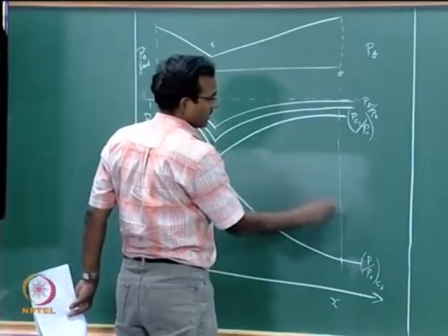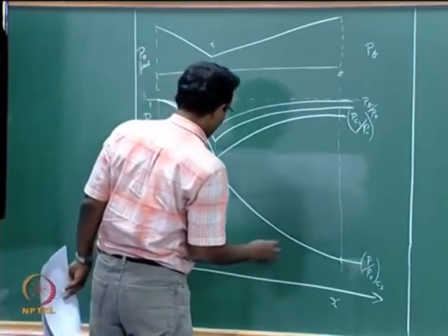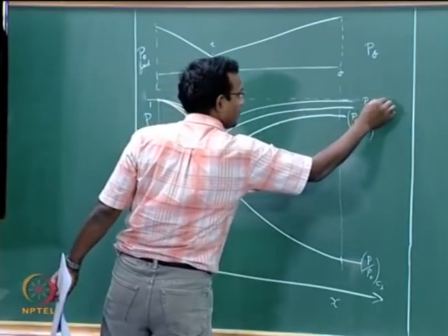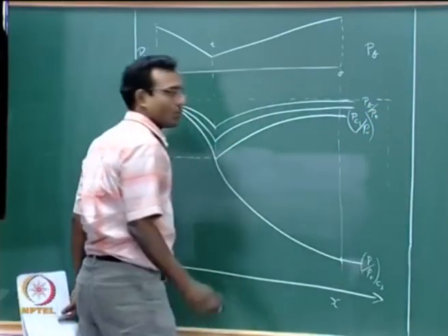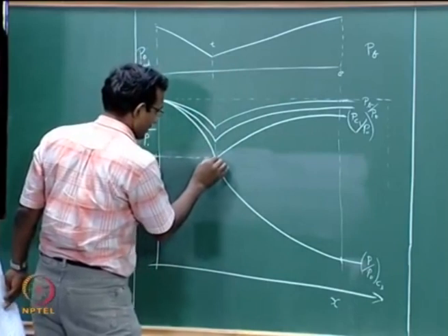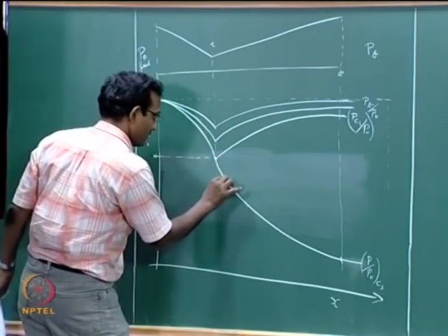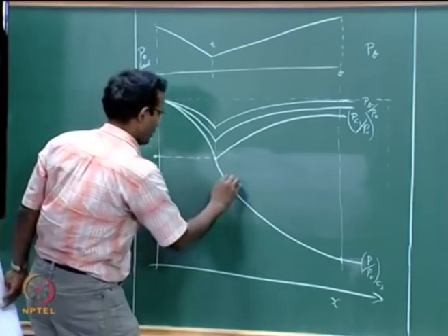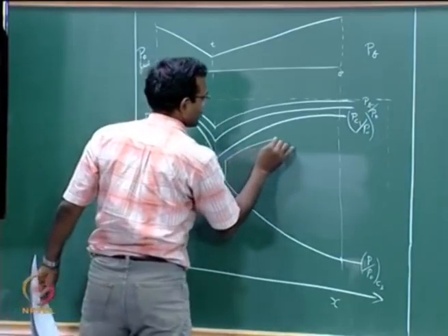And anywhere inside, the flow is not fully isentropic, we said. So, if I start from Pb by P0 equal to 1 and go down slowly, I will go to a point where suddenly the flow becomes supersonic partly, and then it realizes that it cannot reach that pressure. So, it goes through a shock, becomes subsonic, and then goes on a subsonic line.